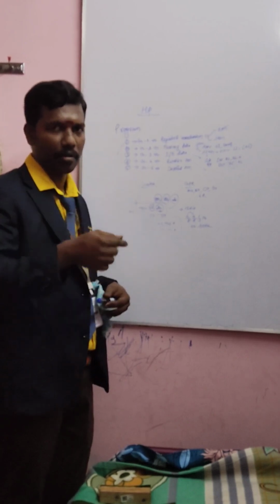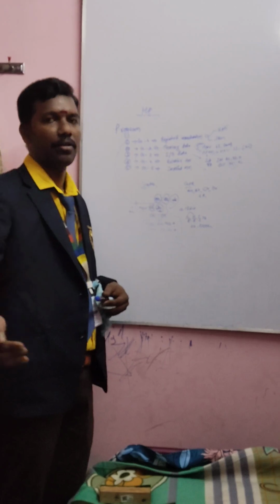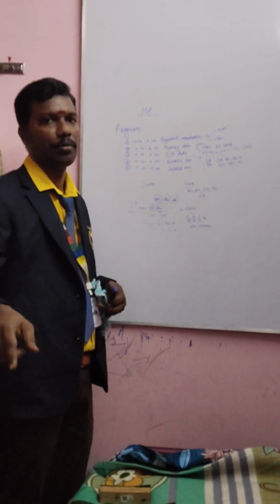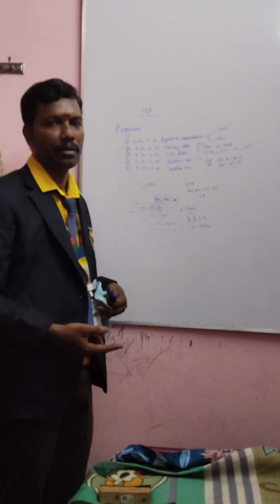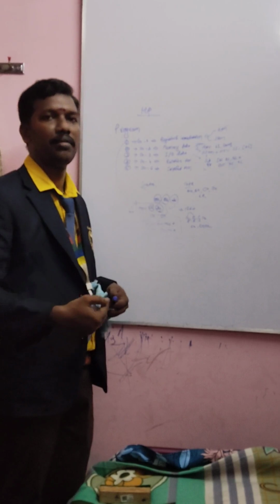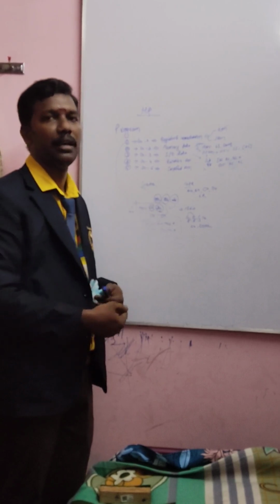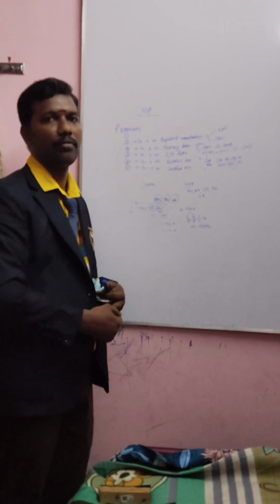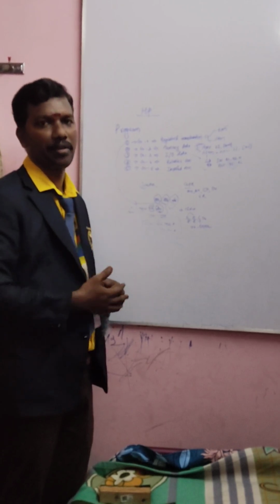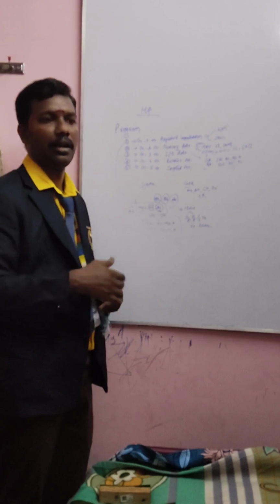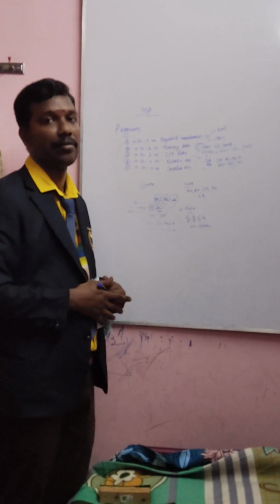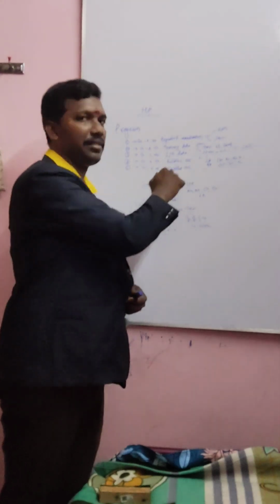So from the regular program, you just discontinue and move to the particular loop, and from the loop, you just call the opcodes one by one. Based on the opcode, we rotate the stepper motor clockwise as well as anti-clockwise. So based on that discontinuity, some no operation will be needed. During this period, the continuing program will jump to one location and call back. So jump, compare, calling, looping, that kind of instruction. Many types of instructions for calling data come under relative addressing mode.